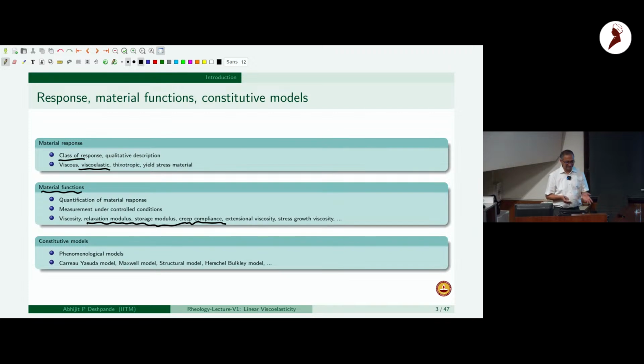Similarly in rheology, there have been several definitions of different variables, and since we also have control over stress or strain rate, we can keep either of them constant and then measure the others, and therefore define all these different material functions. And then in parallel, we look at some model which gives us some grounding in terms of the response compared to the real material that we are trying to organize.